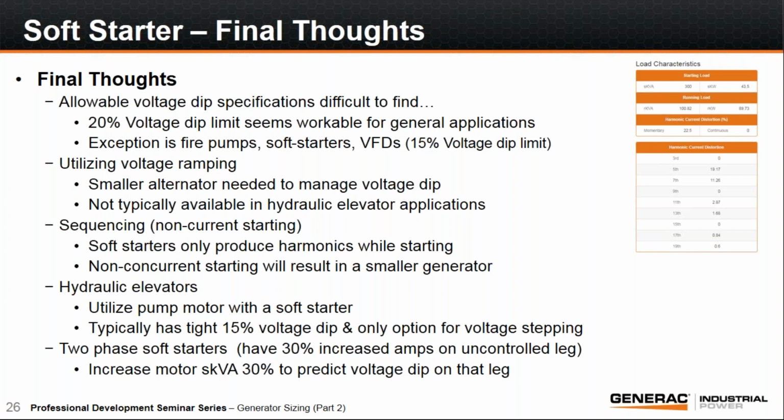Anytime you can sequence your soft starters, do so. A soft starter will produce harmonics during the starting phase, but once the soft starter is fully up to speed, the harmonics go away.